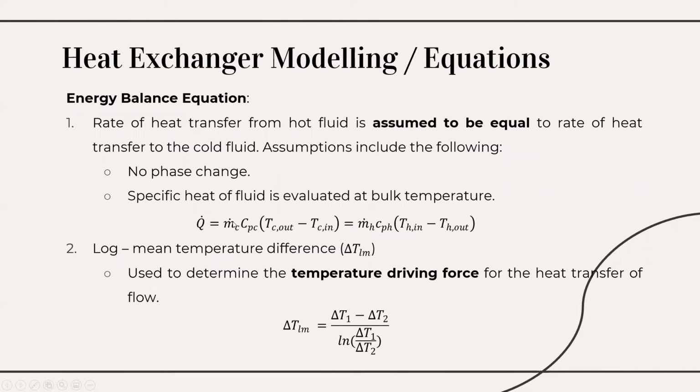The rate of heat transfer from the hot fluid is assumed to be equal to the rate of heat transfer to the cold fluid, with an assumption of no phase change, and specific heat of fluid is evaluated at bulk temperature. This can be expressed in terms of mass flow rates, specific heats, and inlet and outlet temperatures, which can be shown in the equation below.